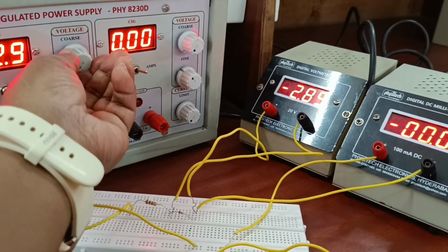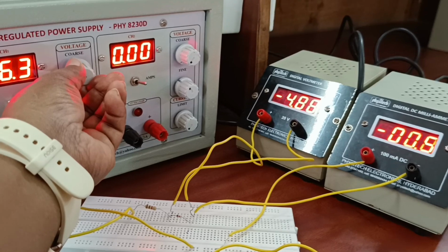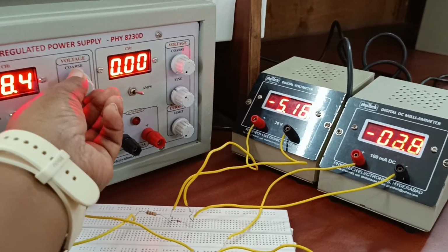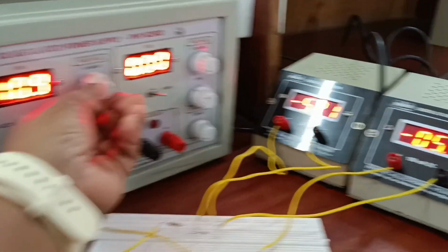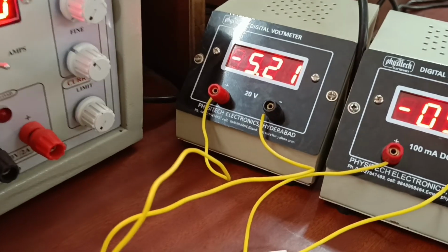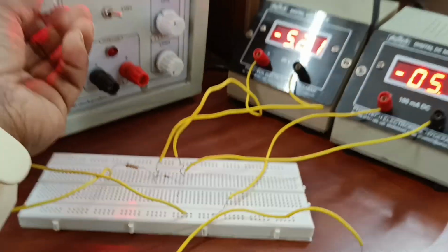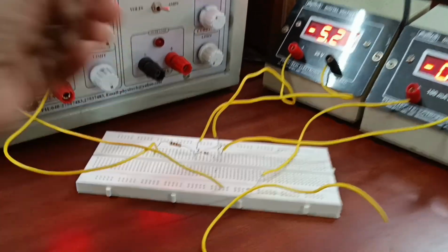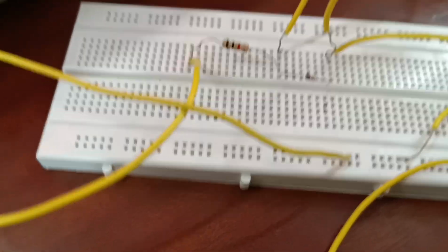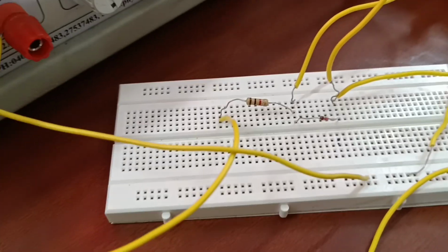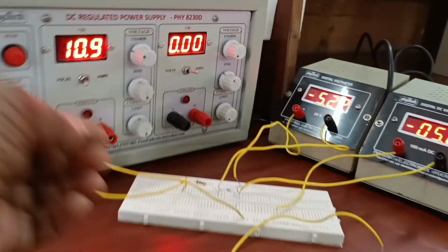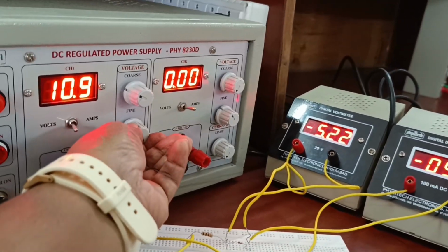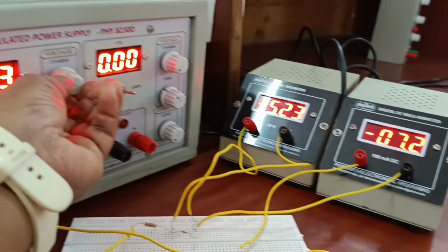If you observe, again 2.9 is not changing. Whenever I give higher voltage, the current slowly increases. Even when I have given 10 volts, it's showing a voltage reading of 5.21. It is called the Zener constant voltage. We have different Zener diodes, constant voltage diodes. In our laboratory, we are using a 5 volt constant Zener diode, so here the voltage is constant at 5 volts. If we use a 12 volt one, the voltage is constant at 12 volts.